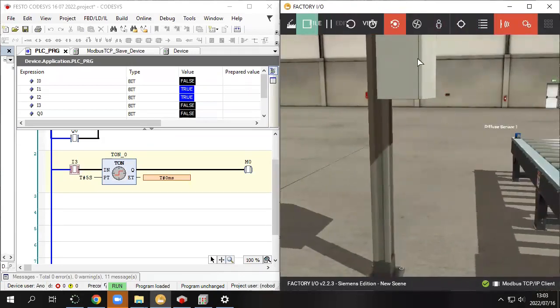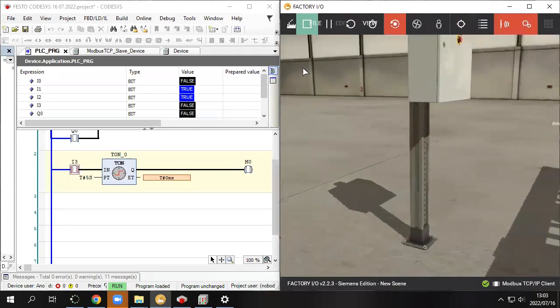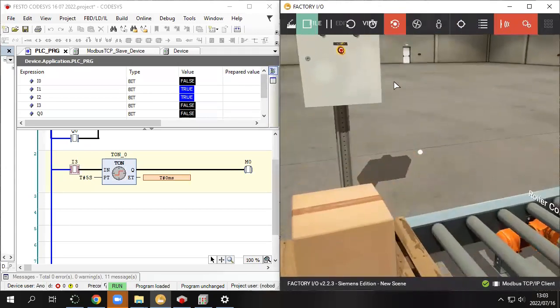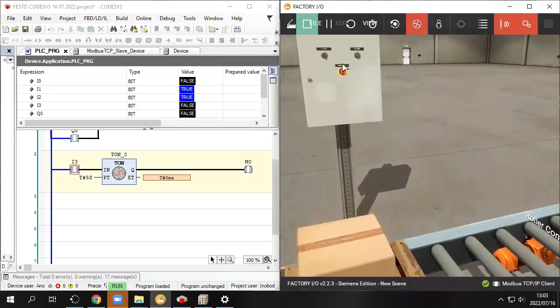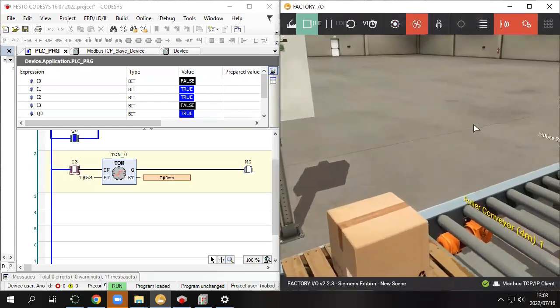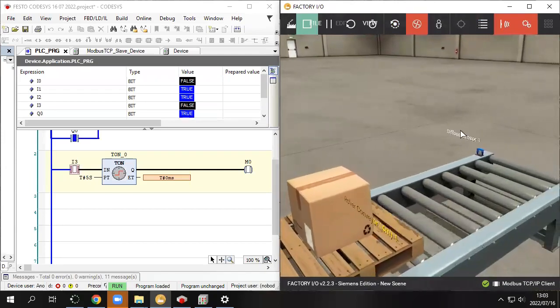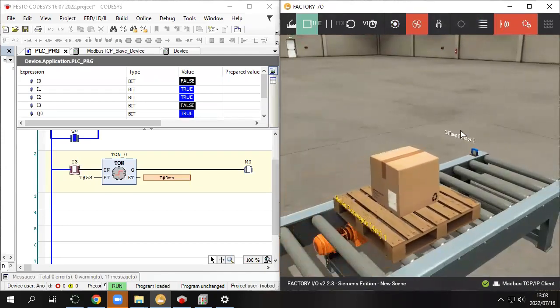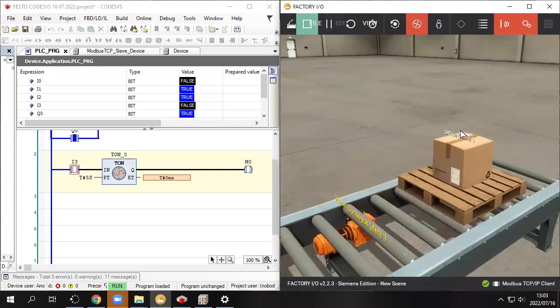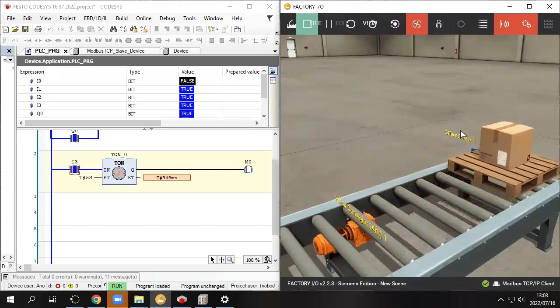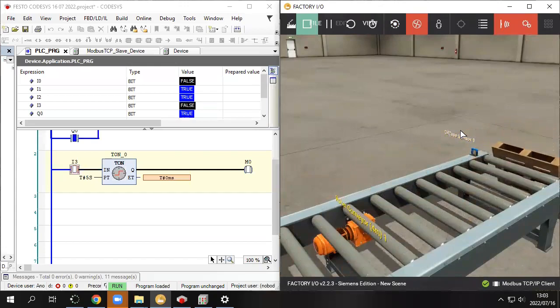Okay, then with reset, okay, number one. So let's put it on the side profile. Nice. Change this. Okay. Cool. So let's see what it will do when it gets to I3 there. I3 starts to count. It counts, then it falls. Then look, it couldn't finish counting. The conveyor belt still runs. You see? So when we retain it, we'll give it a chance to really run until it finishes.